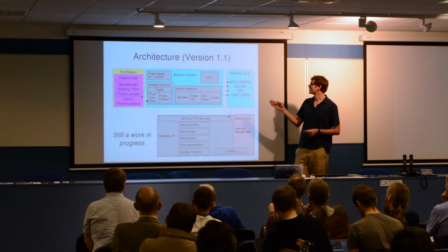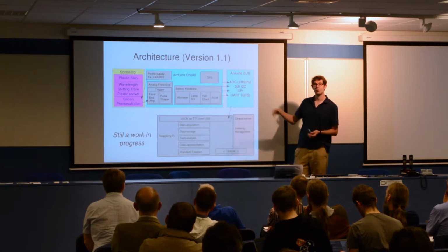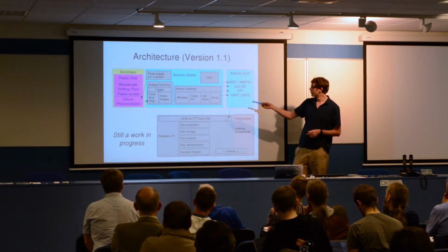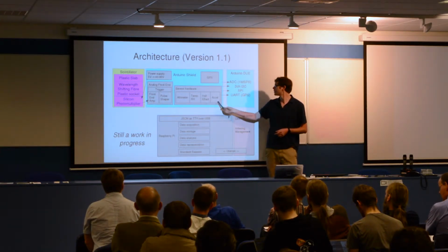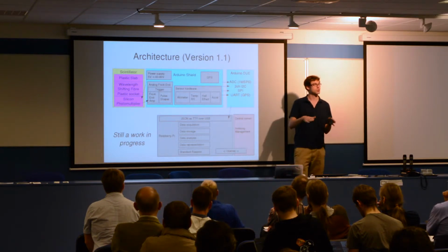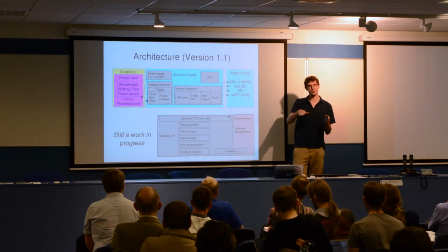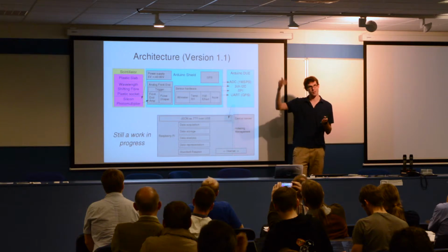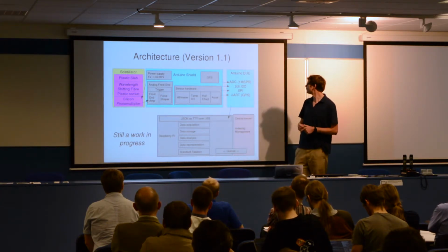Now we've moved on to a slightly different architecture, version 1.1. The scintillator slab is effectively unchanged. We're now using Arduino, and we're looking at making our PCB as an Arduino shield, with some augmented sensor hardware as well. We've added an XYZ magnetometer, Hall effect sensor, and an accelerometer, which enables us to get the orientation of the system, so that we can actually see where the slab is in relation to the surface of the Earth. Because, for example, if it's on its side, the parameters of the cosmic rays arriving will be detected differently, because they'll have a different cross-section to the detector medium.